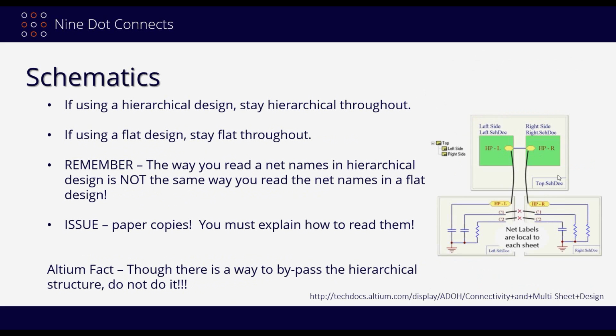And this becomes problematic because most people are looking for net names, and if they see the net name on page 1 and they see another net name with a similar value on page 10, and they don't understand the concept of hierarchical design, and pardon me if I'm pronouncing it wrong, then they may be saying, hey, this thing over here is supposed to talk to this thing, and it's not talking, and then find out that actually, that's not how they're supposed to talk. Now, it may not cause a lot of issues in terms of respins and those types of things. It may prolong the test, and it's going to cause delay.